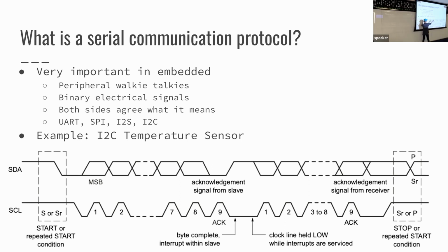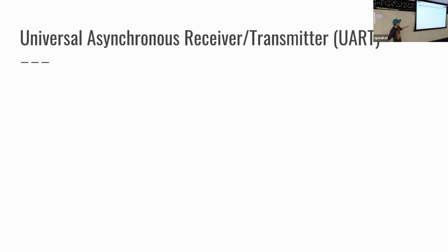And so this is one integer that says 20 degrees Celsius or something, and then this clock line here is the receiving end, how long each of these bits is, because this could be a 0, and then another 0, and then a 1, and then another 1. But without this clock line, you wouldn't know if that was 1 long 0 or 2 zeros in succession. So the receiving end can use that clock line to coordinate the various bits in a particular byte. The synchronization.